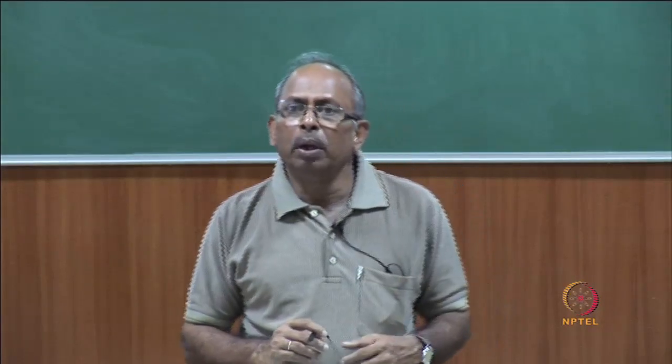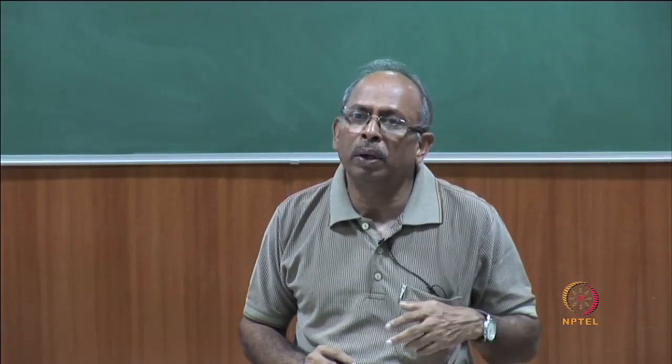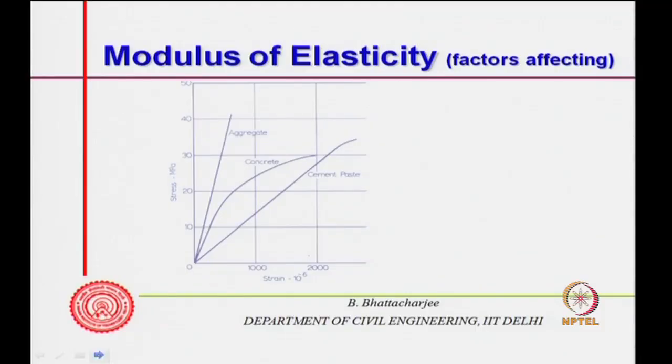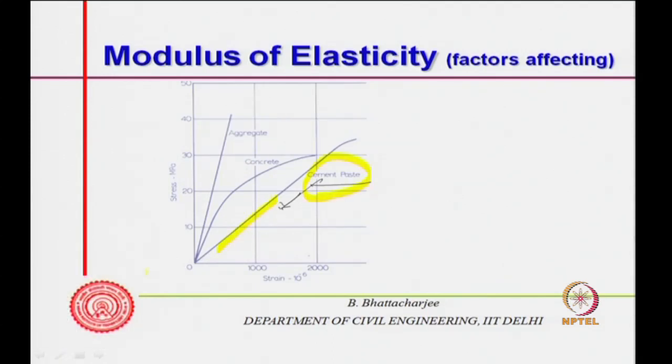So, now let us look at the factors affecting the modulus of elasticity. First of all, you see here the stress strain curve of cement paste, and this is the stress strain curve of aggregate, which generally would show something like that, and concrete shows a stress strain behavior of this kind.